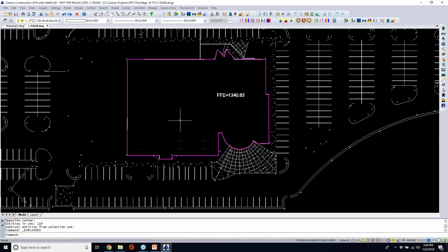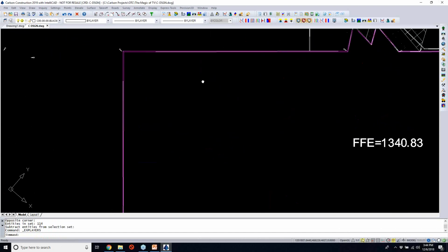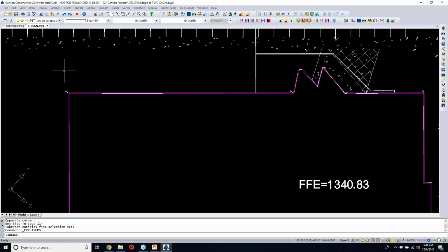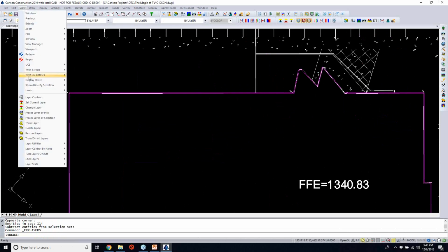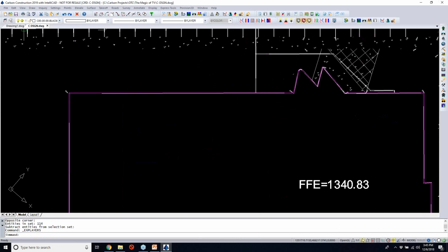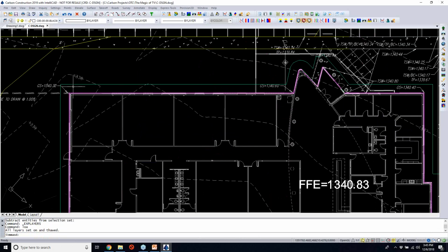So with this polyline boundary drawn in now, I could offset it, and that was a quick, easy way to draw that polygon boundary in there for me. Then from here, let me go back now and do my view through on all layers. The result was that I offset it 5 feet, and that's what became that green line that I had in here. And you can see that offset boundary right there.